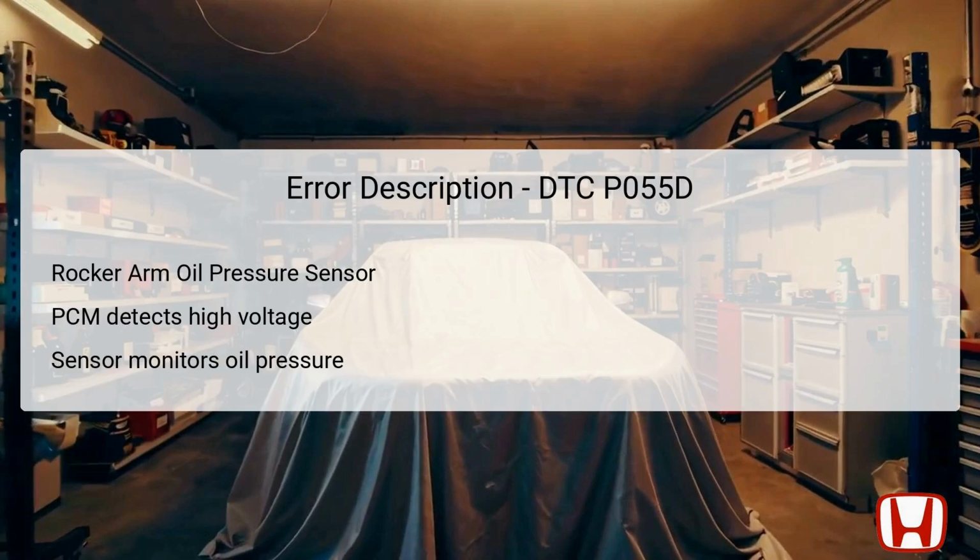The rocker arm oil pressure sensor is integral to the engine's function, providing real-time data about the oil pressure within the rocker arms. If the output voltage from this sensor exceeds specified limits, the PCM recognizes this irregularity and triggers the DTC P055D. The sensor's role is crucial as it helps maintain efficient engine performance, ensuring that adequate oil pressure is delivered to the rocker arms.